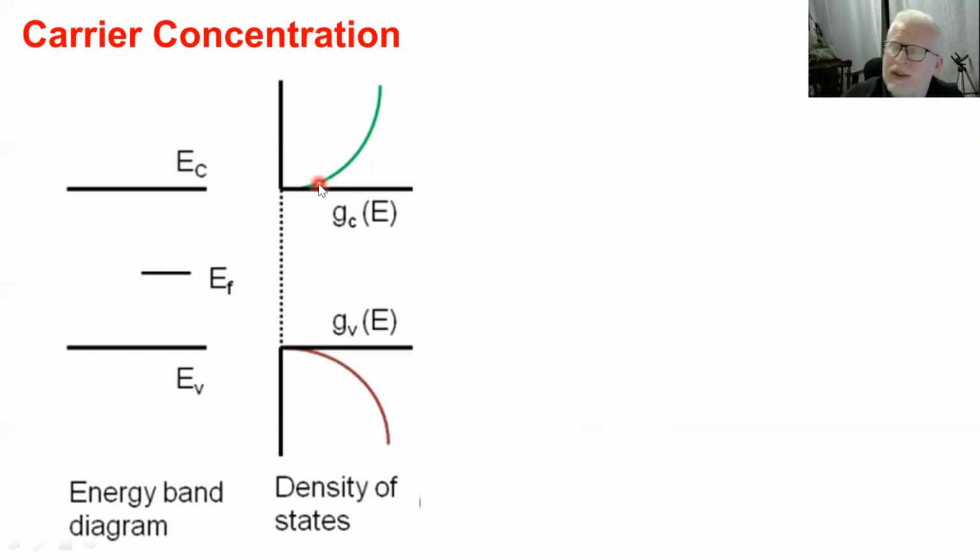And as I mentioned in my previous lecture, in our course, as far as we are not dealing with the quantum principles, we will not investigate how this function has been determined. So we will consider it as a constant function with respect to energy, demonstrating the available seats or the available states of the electrons in the conduction band. Similarly, you can see another function in the valency band that also demonstrates the available seats of holes. Again, this function is only defined in the valency band because holes are only defined in the valency band.